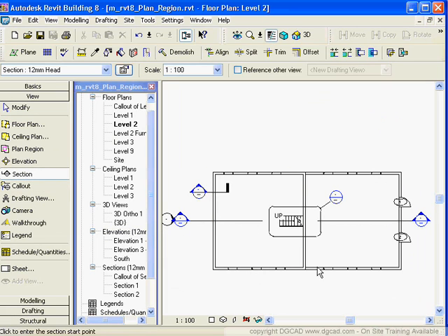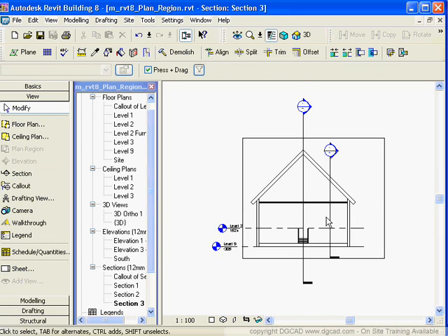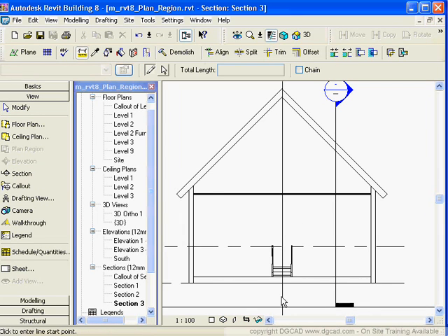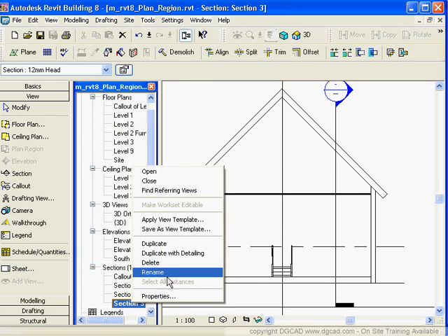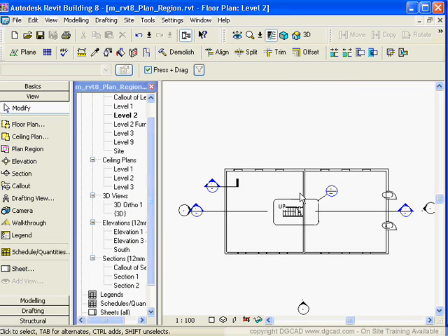So that's creating, back to doing our sections, putting a section in as many as we want. We do a lot of sections just to check things. We just click on there, we do a section, and then we might go in, zoom in, and use our distance command to measure from here to here. It's going to tell us how far it is. That's all good. We can measure some distances across here. It's created that section down in here.